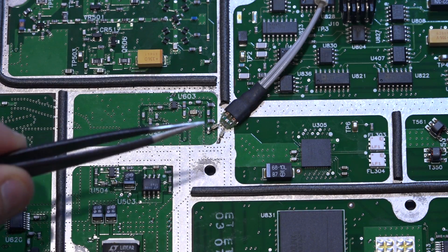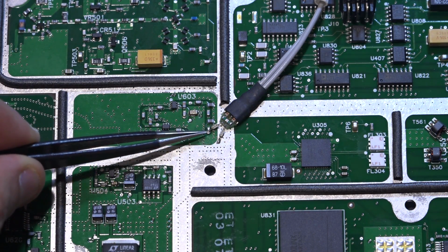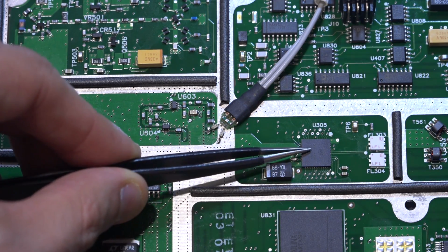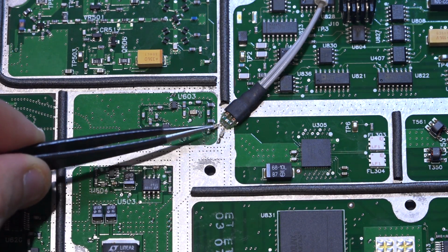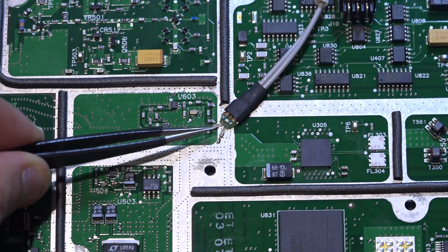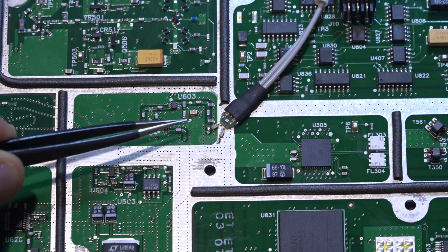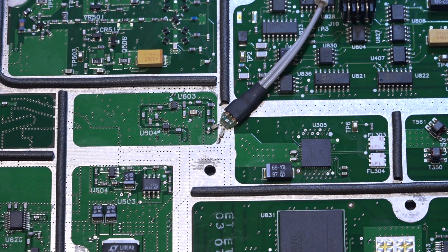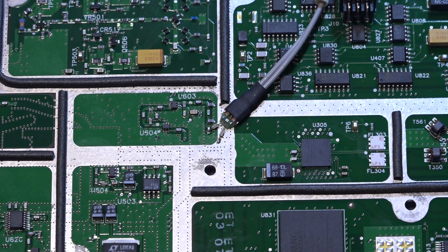Okay, here is our active probe connection. You can see this is the node that is fed onto the programmable divider, the chip from ON Semiconductor, and here's the ground. So there you go. We have now a high impedance active probe connection. This thing should have up to about 8 or 9 gigahertz of bandwidth the way it is set up. I'm going to tape this down, and we should be able to hook it up to the scope and actually see the waveform there. And as we sweep the frequency, we can look at the quality of the waveform.